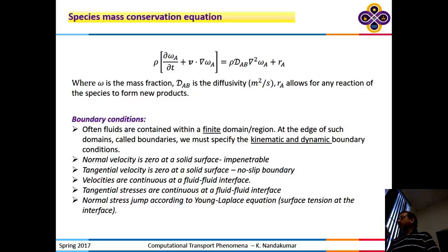At the molecular level, when it hits the wall, its tangential momentum is going to be taken away. It may rebound if it is elastic and go away, but it's not going to slide past it. So the zero slip condition is a good assumption for such small molecules.